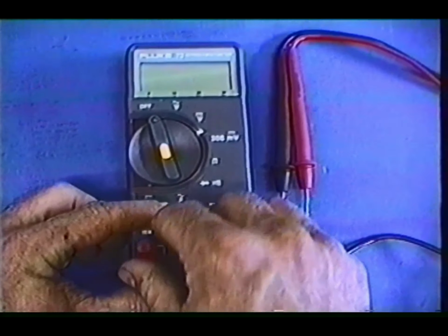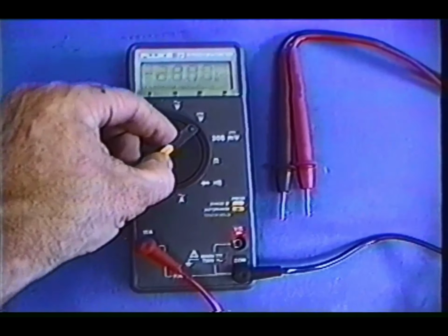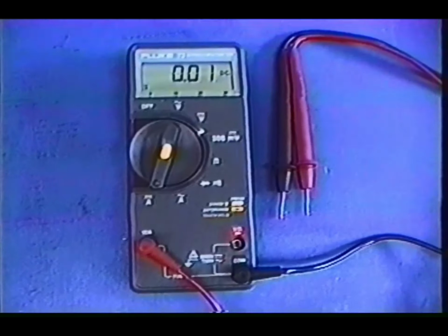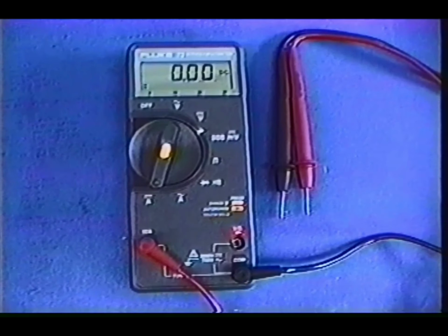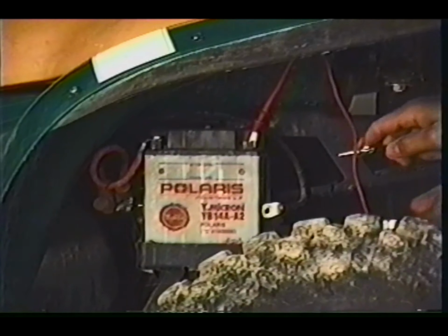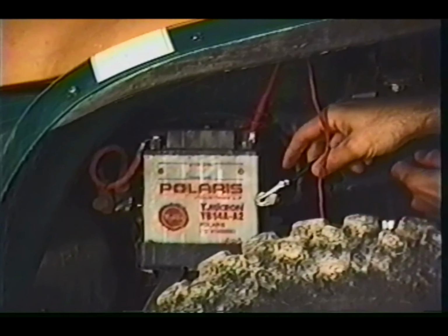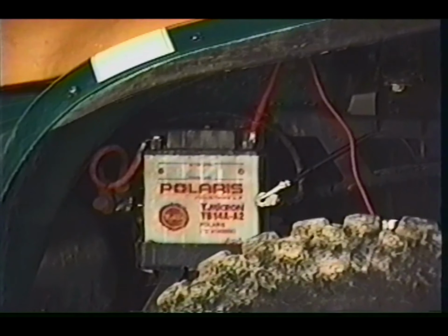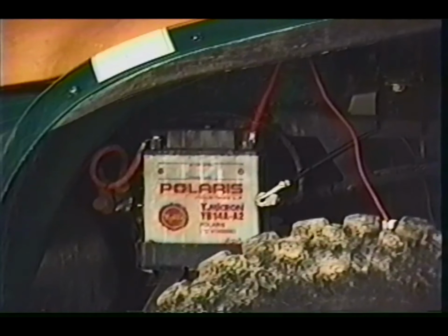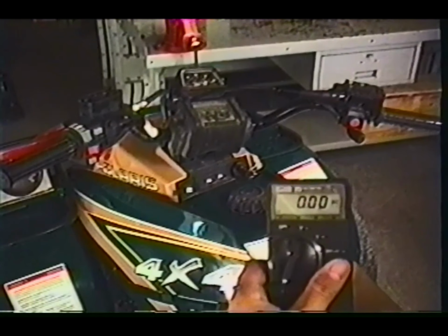Everything to this point can be functioning properly, but there may be a residual current draw with the key off. To check this, we need to connect the Fluke amp meter in series with the battery ground cable. With your selector dial on DC amps, connect the red lead to the 10 amp hole on your meter. Then connect the red lead to the battery and the black lead to the ground wire going to the frame. With the key off, you should read less than 0.02 amps. A higher reading indicates excessive current draw. Disconnect non-standard accessories first and then other system components until the excess current goes away.